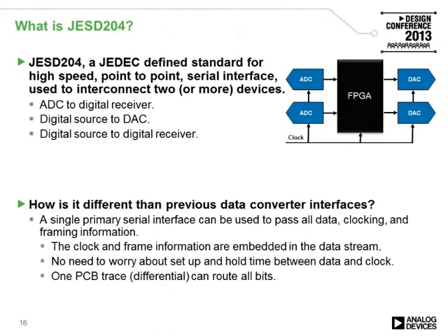SerDes, short for serializer deserializer, is sometimes used instead of JESD204. SerDes is simply a generic name for any serial interface. JESD204 is a JEDEC-defined standard for high-speed, multi-gigabit point-to-point serial interface used to interconnect two or possibly more devices.